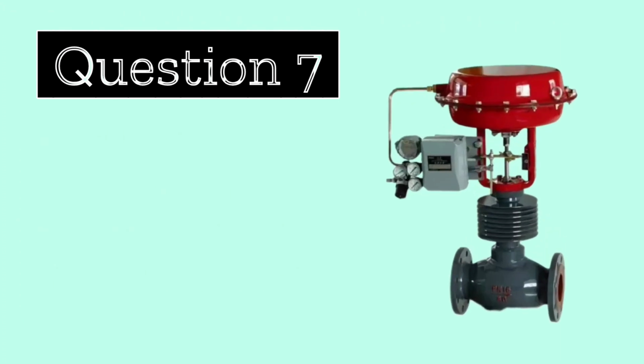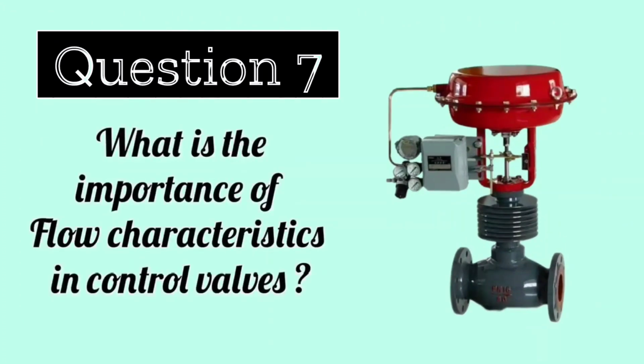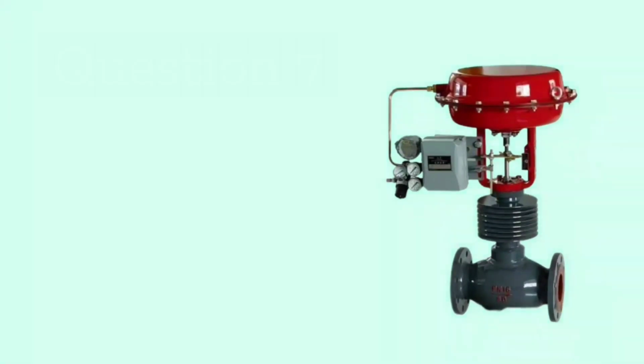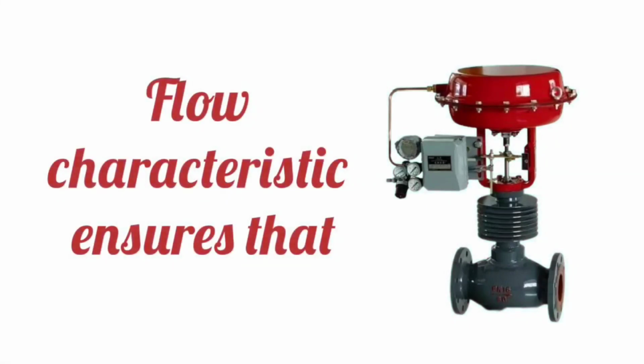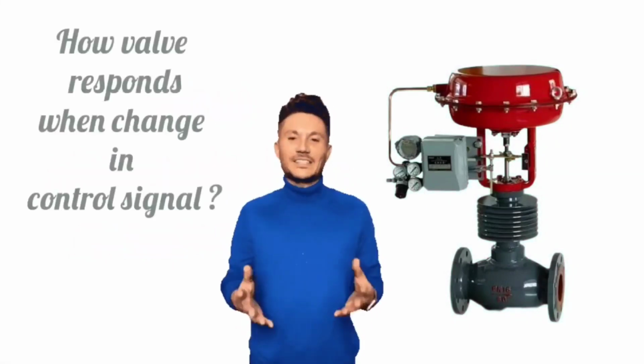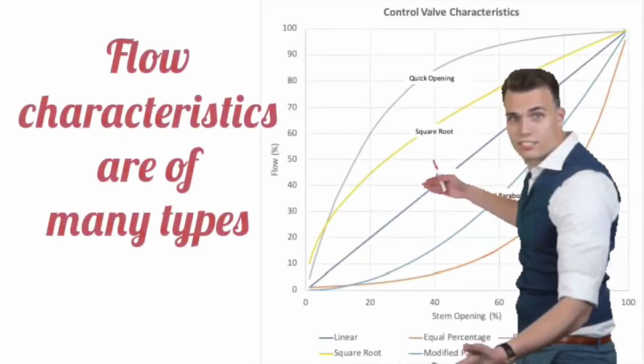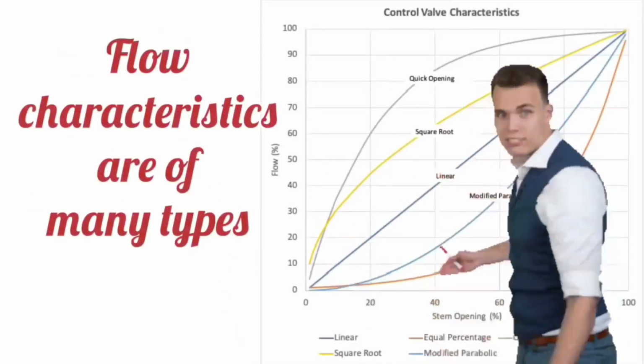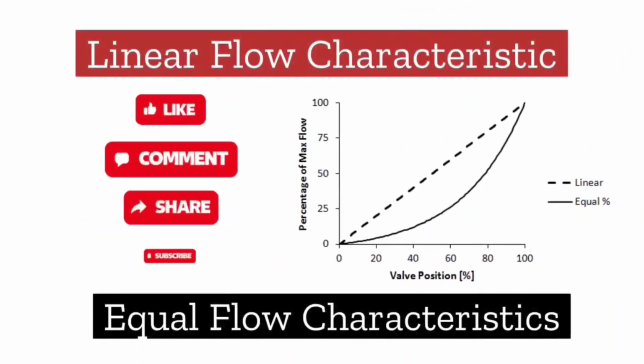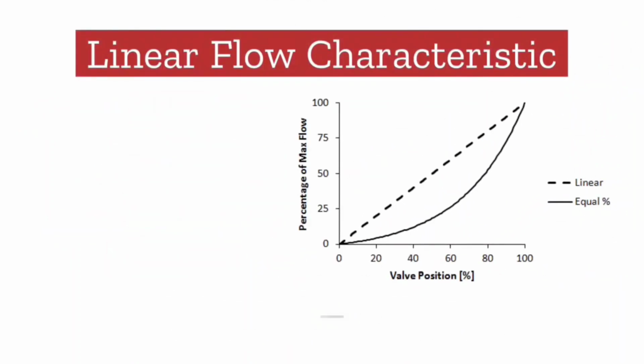Let's take the next question. What is the importance of flow characteristic in a control valve? The flow characteristic determines how the valve responds to changes in the control signal. There are many types of flow characteristics, but we are going to discuss linear flow characteristic and equal percentage flow characteristic here. Let's discuss linear flow characteristic.